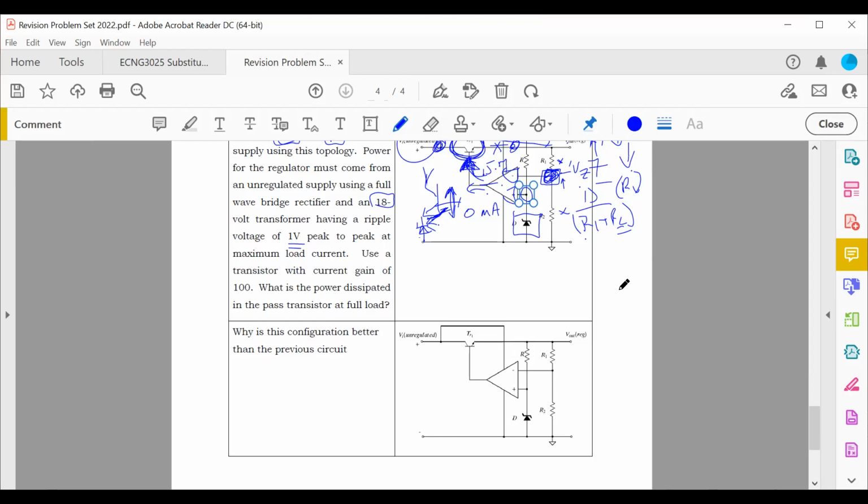Yeah, so instead of 25 volts, you're just working with 15. Because of the Zener diode, because it's connected after the transistor now. Before the transistor it's 25, after the transistor it'll be 15.